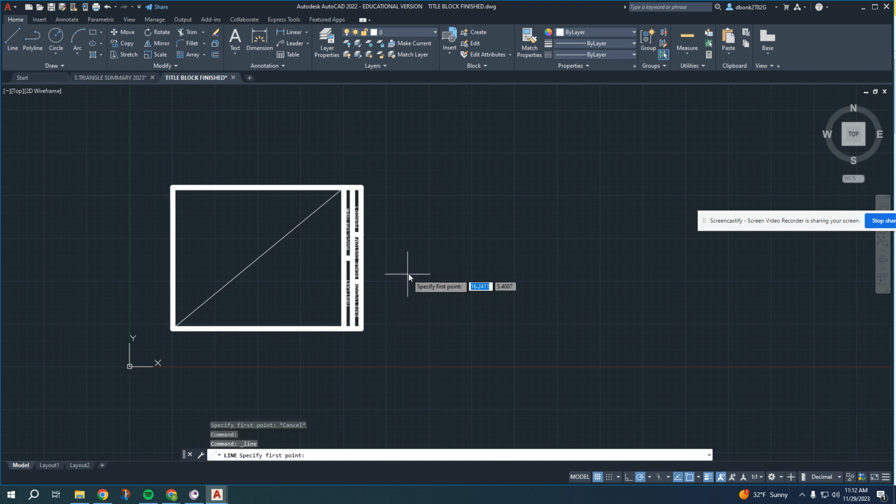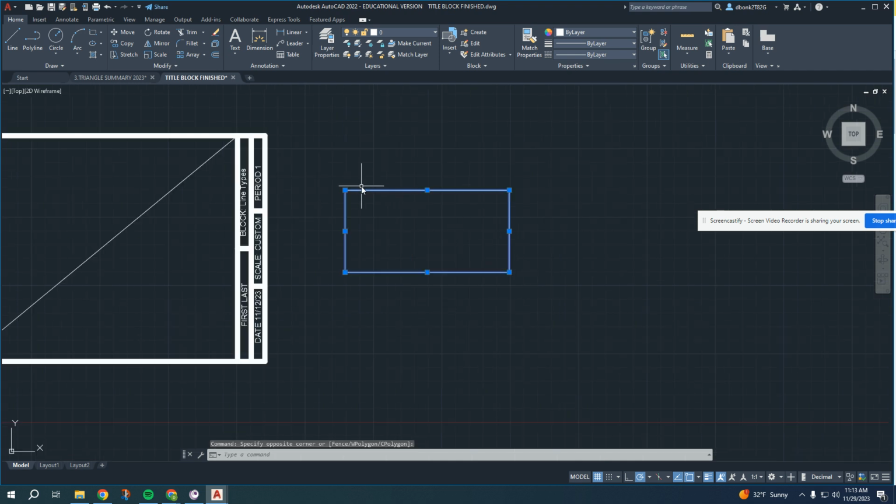So watch this. I'm going to make a 6-inch, 3-inch vertical line, 6-inch back the other direction, close this off. So if I can grab this from the middle and put it on the midpoint of this line, it'll center it. So that happens by clicking on one side, letting go, and then clicking again to do a selection. You have to make sure that you see these anchor points. So there's ways of doing selections where you just see a blue line and not these anchor points. That's not good. You need the anchor points. Then you go to move this box.